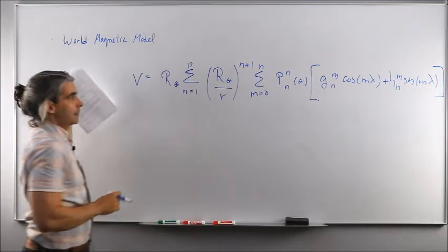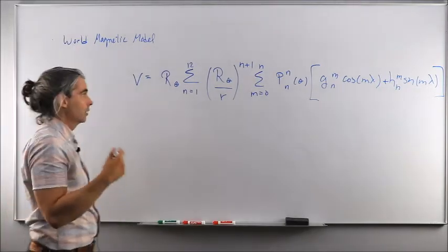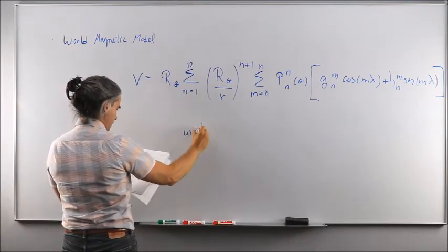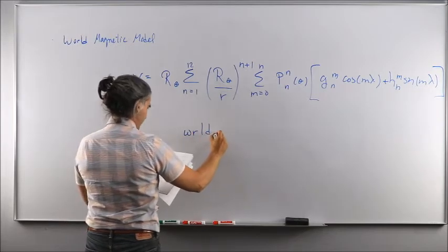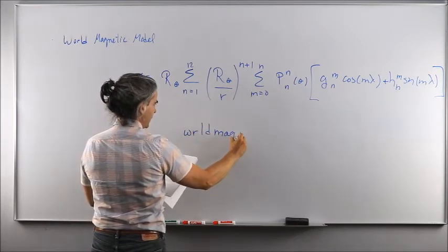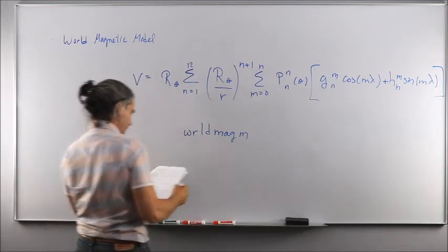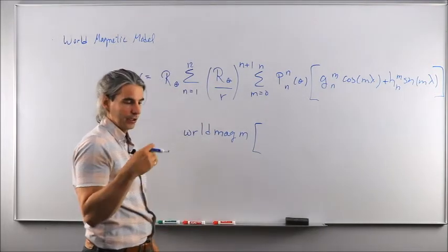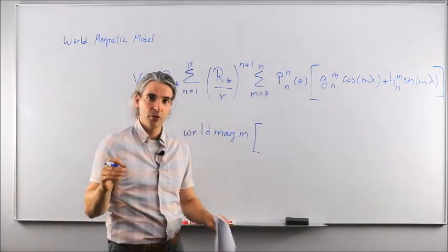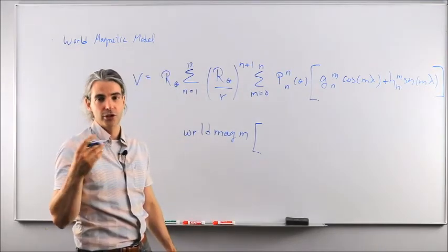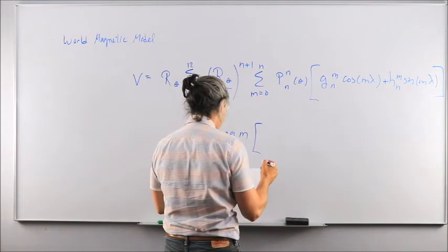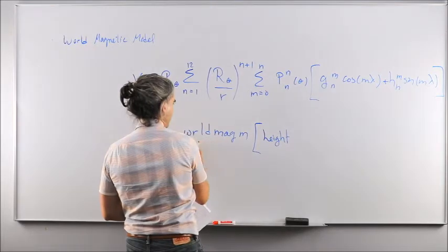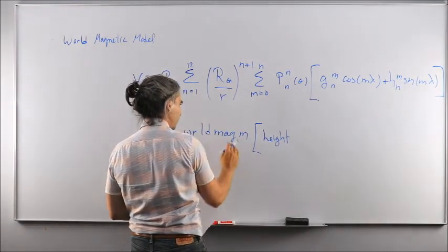And the beauty of that is that MATLAB has a built-in function called the world magnetic model that you have to type as WRLD for world, mag, the magnetic, and M for model, that based on the current spacecraft altitude above the surface of the Earth, so you need to take the magnitude of your position vector minus the radius of the Earth, which is your 6,378 kilometers. All right, so that is the first parameter you need to give MATLAB to evaluate this world magnetic model function.